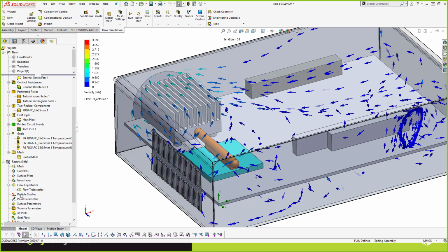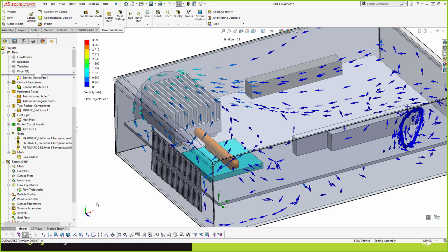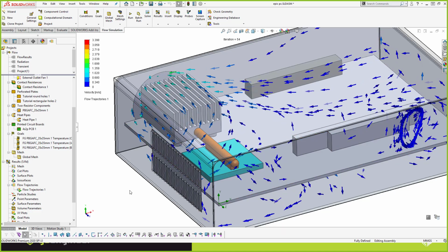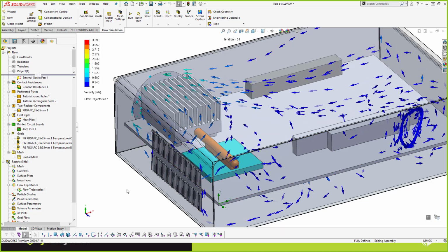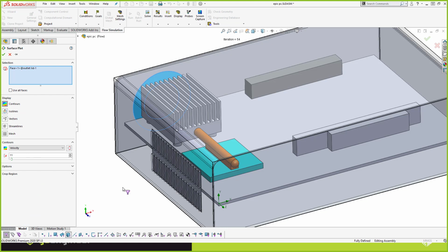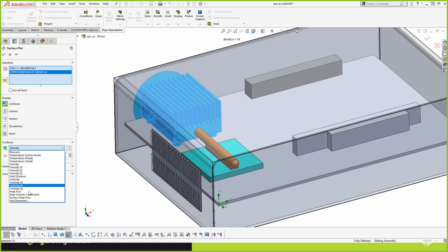Okay, so I can see air flowing, how it flows around this domain. We see some recirculating going on back here, not much going on back there. So we're actually modeling that air, and with the air modeled in here, we can see things like convection coefficients. Let's look at the convection coefficient on this body, because we assumed 20. That was the assumption in our hand calculation. How good was that assumption?